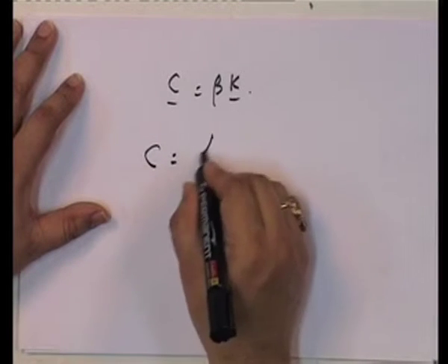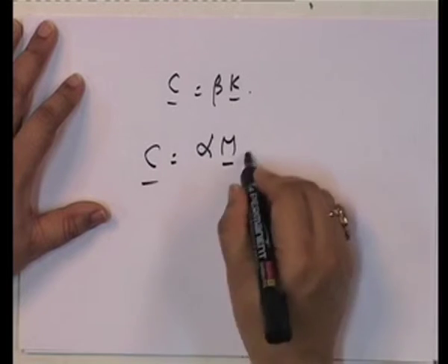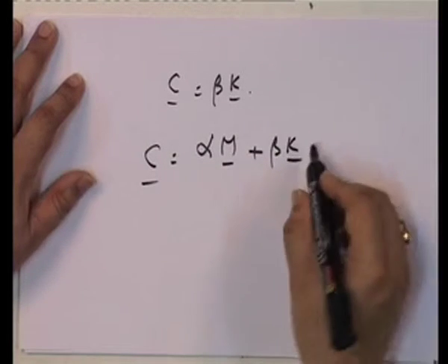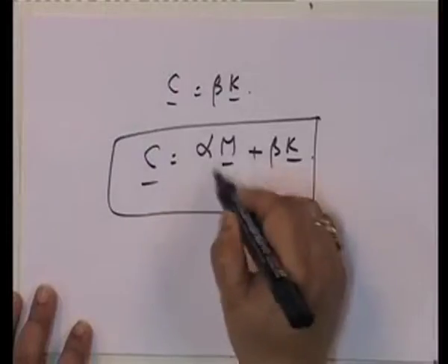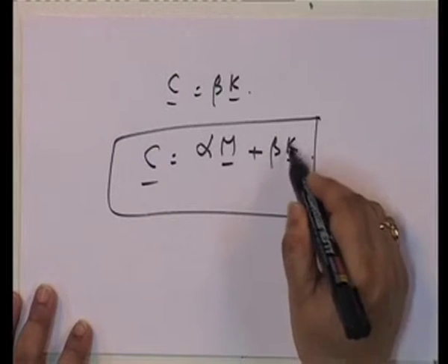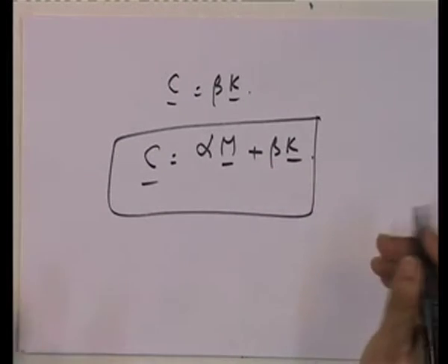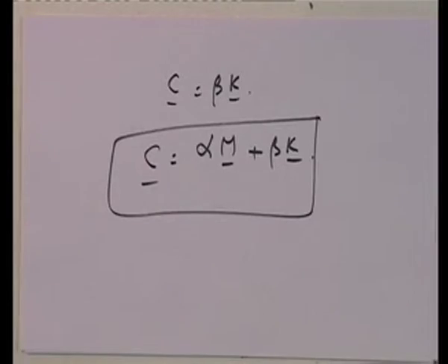And then we talked about Rayleigh damping, remember last time? Well, it's obvious, I am not going to go through this. Phi transpose will just become phi transpose m plus phi beta into phi transpose K phi. All of those are diagonal.